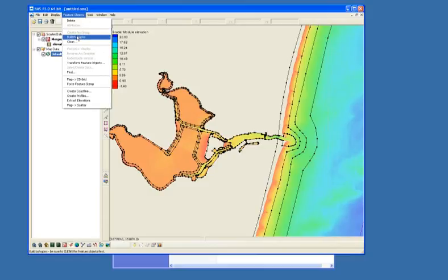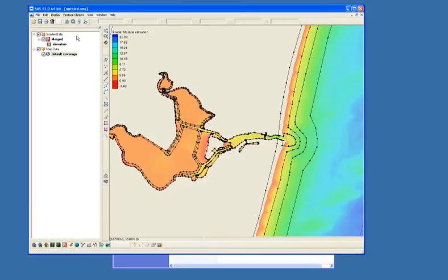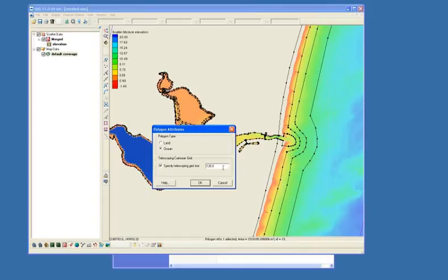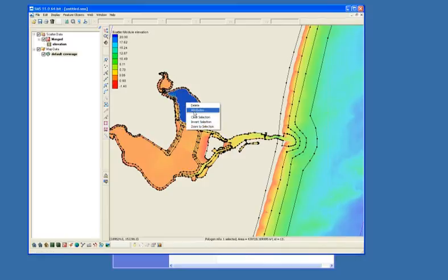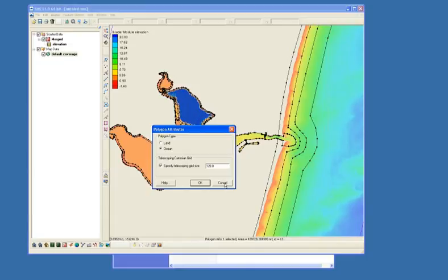And so that takes all the arcs that have closed on themselves or onto the edges of other arcs and creates polygons with those. Then you have an ability to select those polygons. So I'm going to select this one. I can either double click on it and specify a value, or I could right click on it and choose Attributes and specify a value.